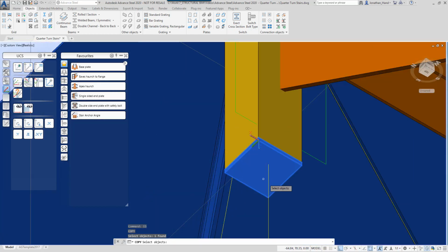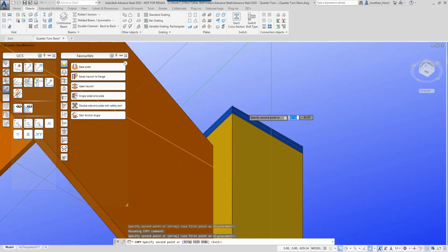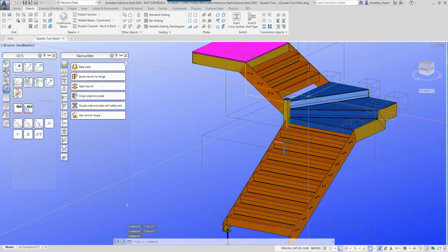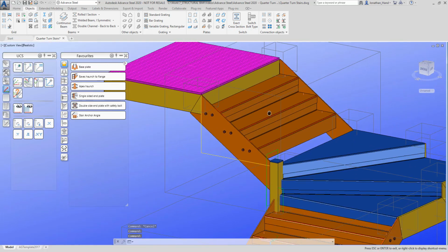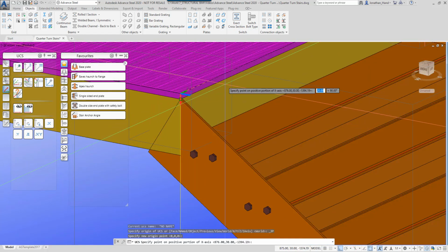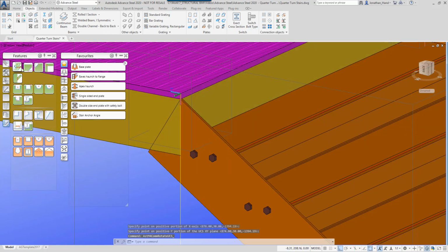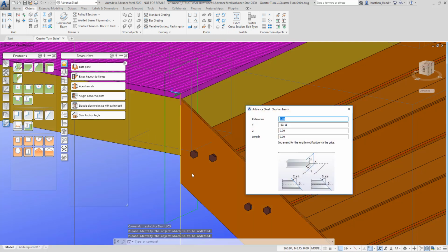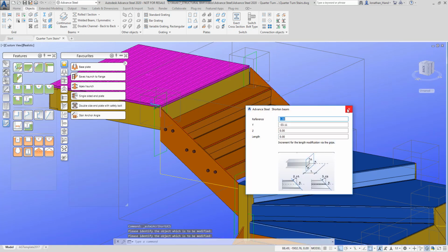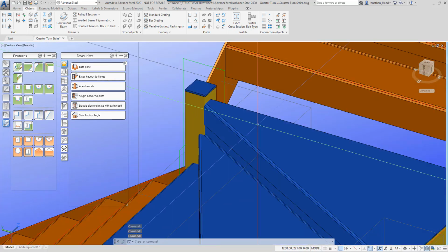and then I could copy that object, let's say up to there. So we're getting up and round, and it's just this top section here as to what we're really going to do with it. So first things first, I'll put the UCS at the grating and just rotate that around, and I'm going to cut both stringers at that section there, and I'm going to cut that one there. And then we just need to look at what we're really going to do in round this section here.